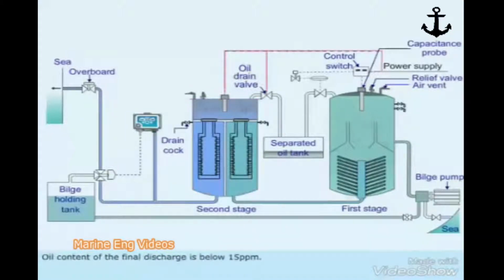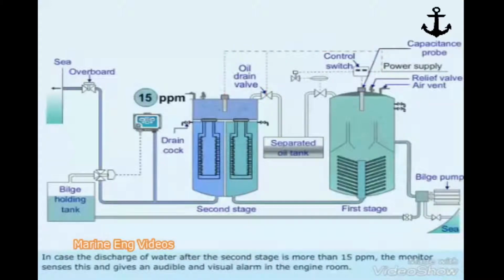Oil content of the final discharge is below 15 ppm. In case the discharge of water after the second stage is more than 15 ppm, the monitor senses this and gives an audible and visual alarm in the engine room.